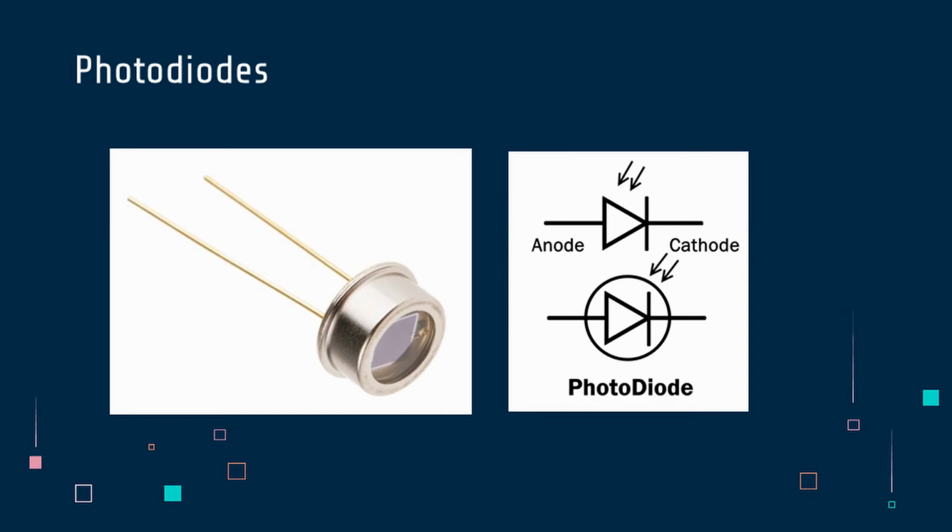In order to discuss CCDs, I'll first discuss how camera sensors work. At a very small scale, camera sensors contain many photodiodes, which are similar to diodes as they often use p-n junctions, but with the difference that they only conduct in reverse bias. Their main purpose is to convert light energy into electrical energy.